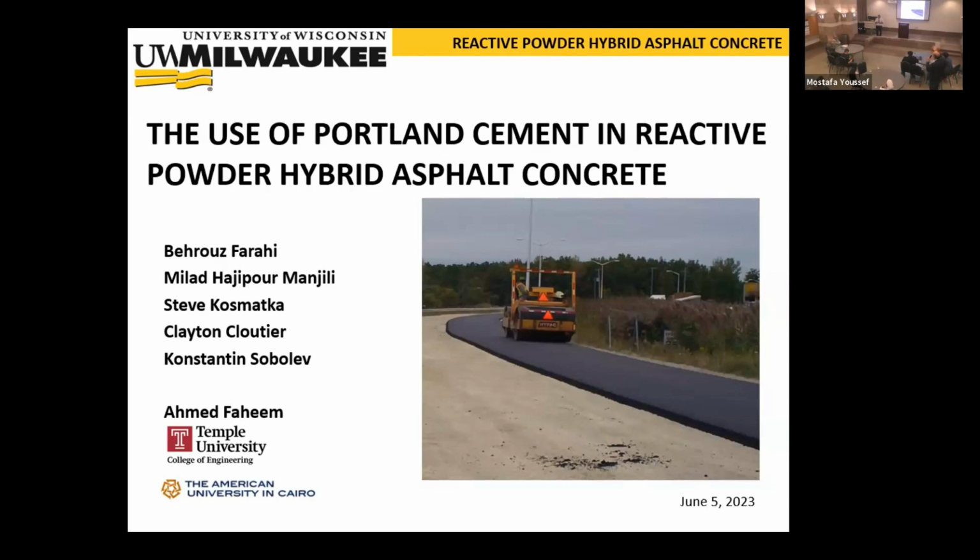We did that with asphalt at that temperature, with fly ash. I was just writing something today, and we realized that the silica content in the fly ash plays a big role. I just remember this now, but this is why we collaborate with Constantine, because that's not my area. I think the measurement will be this density of OH groups at the surface, and that is typical for any oxides, silica in particular. In the case of silica, you have a wide span of possibilities, probably way more than C2S or C3S, the cement grain itself, which is a silica-based particle.